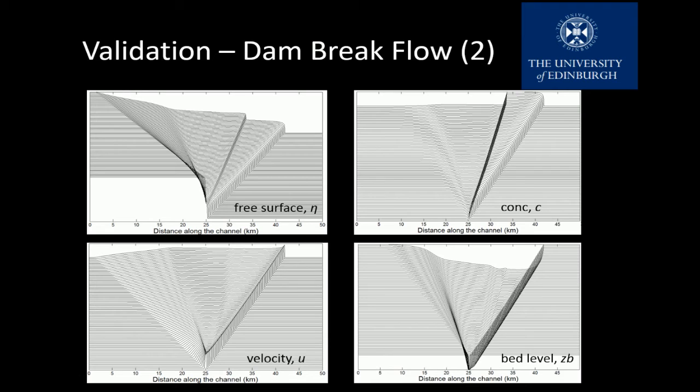And also here, normally if you have a dam break over a fixed bed, you don't have this second front. The reason that this has developed here is because the concentration of suspended sediment falls abruptly. So in order to have mass conservation, you have this increase in water depth.